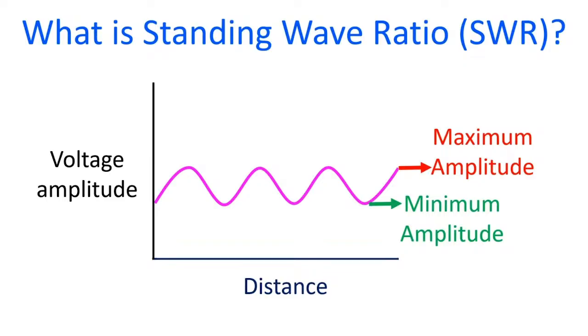Highest level of SWR occurs when the antenna is not connected, open circuit, or when there is short circuit in the transmission line. SWR can be in terms of voltage, known as voltage SWR, and current, known as current SWR. Usually, it is the voltage SWR that is measured using an SWR meter. Ideal SWR is 1 and high SWR above 2 can cause heating of the transmission line and final power amplifier of the transmitter circuit and likely to cause severe damage.